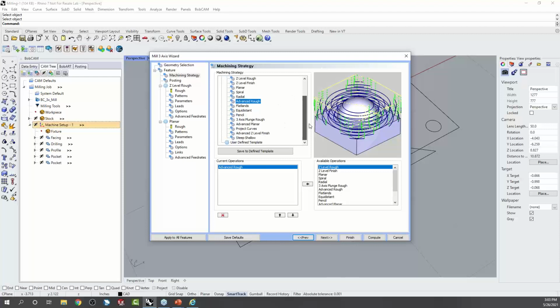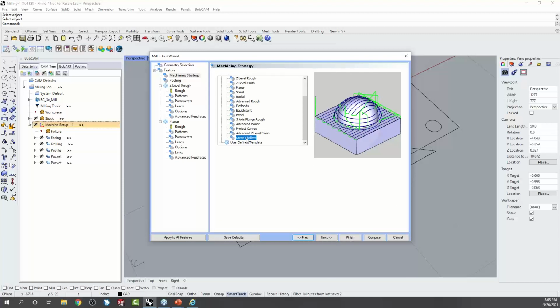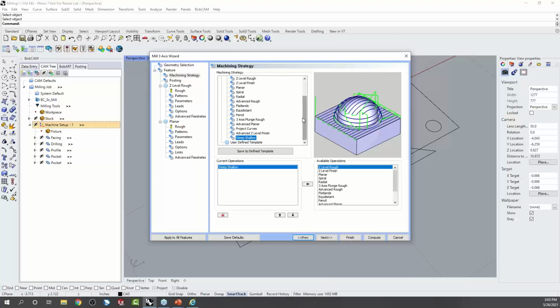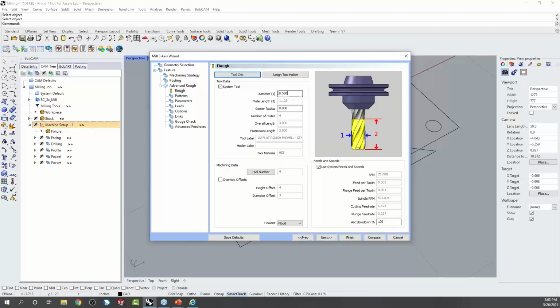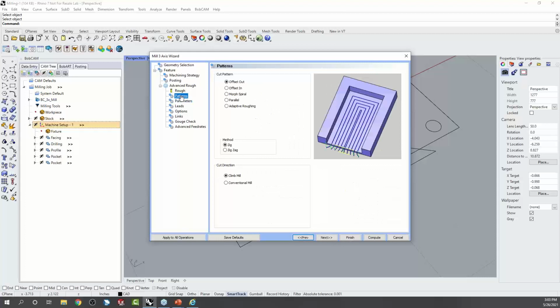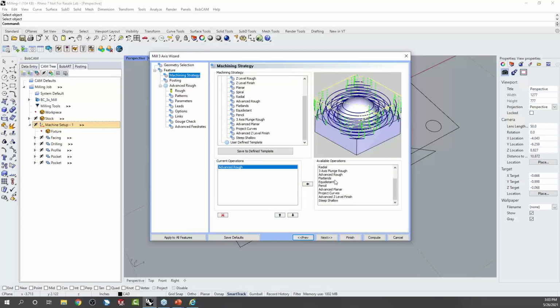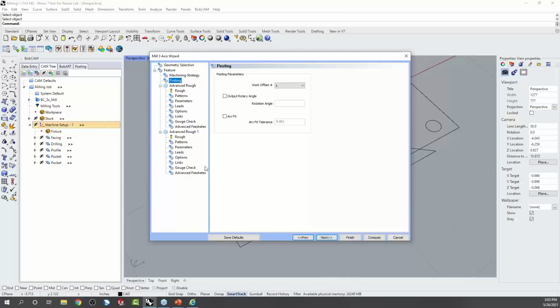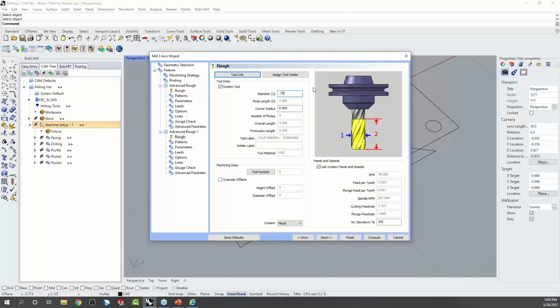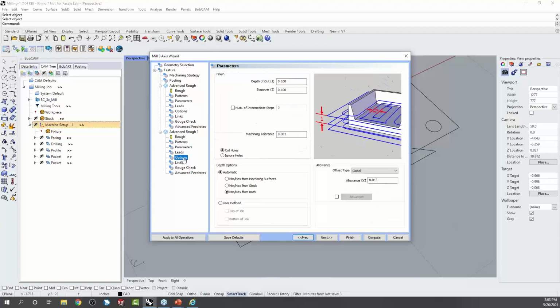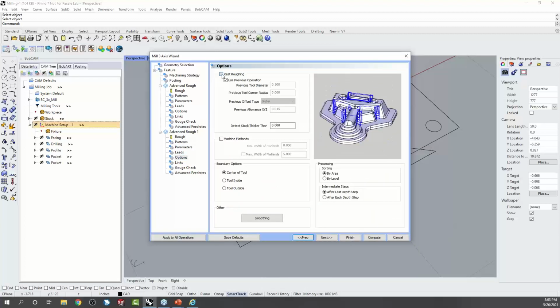These are all of the available 3D operations under the Mill Professional. This one toolpath here is a premium, but the rest of them are all under the Mill Professional software. We're talking about the advanced rough. What he wants to do is come in with a larger tool, whatever size, and rough out your material. So you could do an advanced roughing routine, right? Then what he wants to do is come back with another one. So what you can do is just load another operation there. Maybe it's a 750 cutter. You're going to stage down, right? So when you come into your parameter, or let me see, options here, I could say rest roughing.